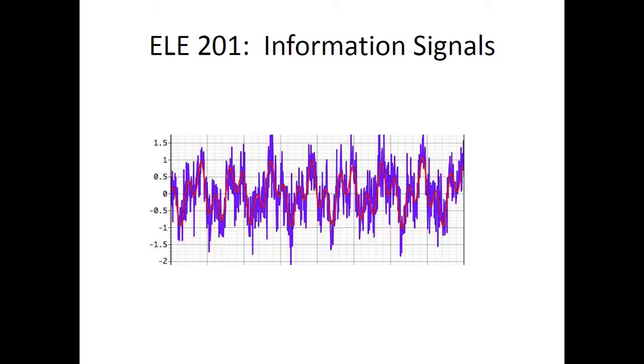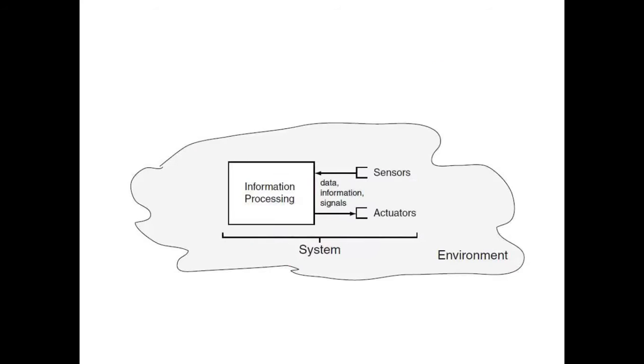A technique where you don't do an average, meaning a mean, you do a median. This is a median filter. And this actually will remove outliers. If you have glitches, really big outliers from your main signal, they should have no effect; the median will kind of get rid of those. All right. So that's a nice, useful technique that is not actually addressed by the mathematics we're going to learn in this class. So there are limits to what we'll learn, but it's also very, very broad. Okay.